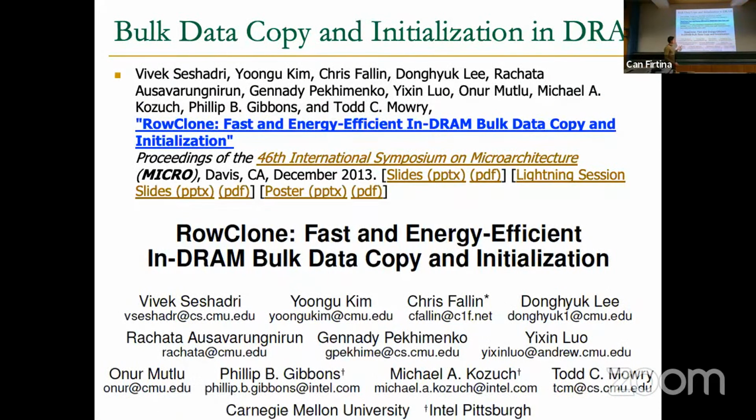Of these two works, I would say that the original idea is not from the Ambit paper. It comes from even earlier, starting to do something useful inside DRAM by just playing with DRAM cells. This idea of RowClone, which for sure we will cover in detail next week, basically opens one entire row, moves it to the row buffer, the array of sense amplifiers, and then by activating another row and writing, it essentially copies the entire row from one row to another. If you try to do that in a conventional system these days, you won't be able because it's basically not enabled, but it's not impossible.